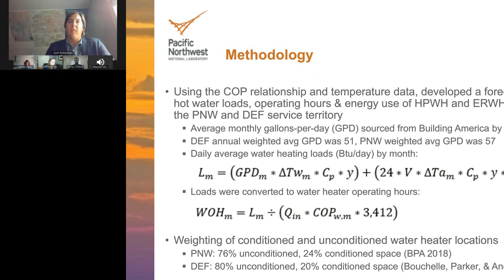So using the COP relationship and the temperature data, I developed a forecast of daily hot water loads, the water heater operating hours, and then the energy use of heat pump water heaters and electric resistance water heaters located in the Pacific Northwest and Duke Energy Florida service territory.